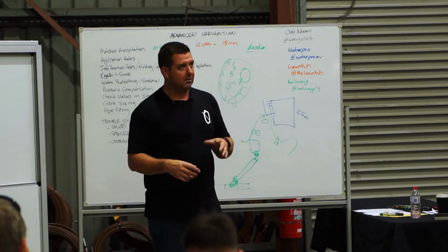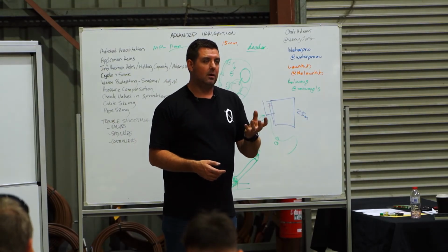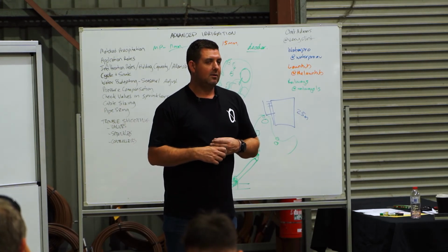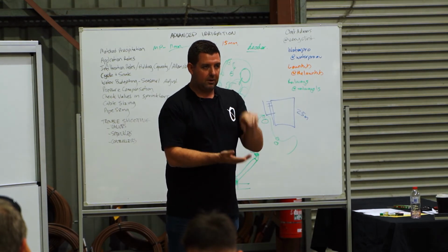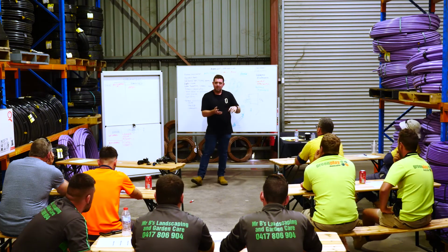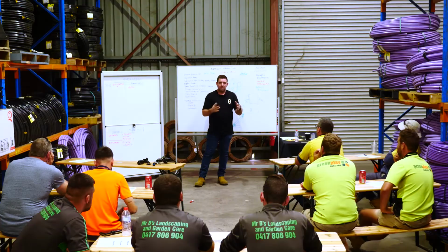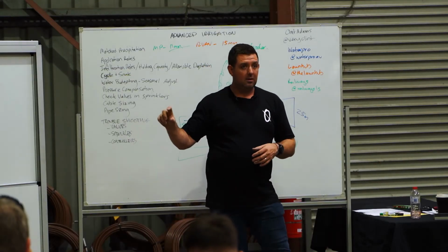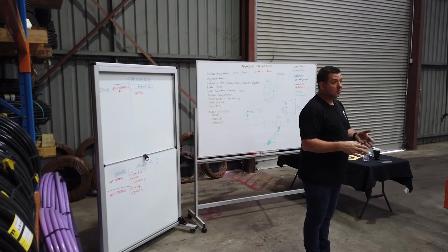So we did a video about this and put it on our YouTube channel. We put, I reckon it was an Orbit Beehive tap timer, and it took that 30 litres a minute of flow to 20 litres a minute just from passing through the tap timer. So we tested that at our Kent Town location with a few different timers. The Hunter Bluetooth tap timer was almost the same. So they're shaving 10 litres. I don't think they shaved 33%. I think it was just a case that 30 went to 20. I think that 40 might have gone to 20.